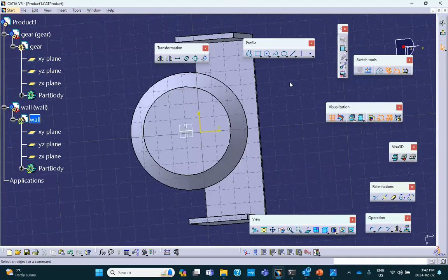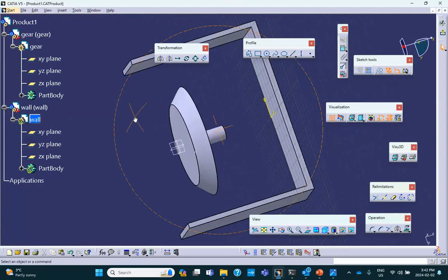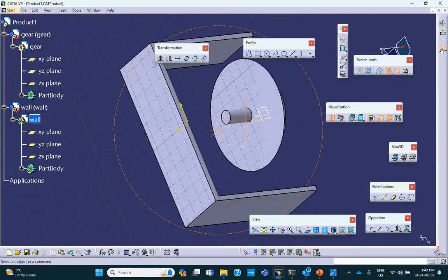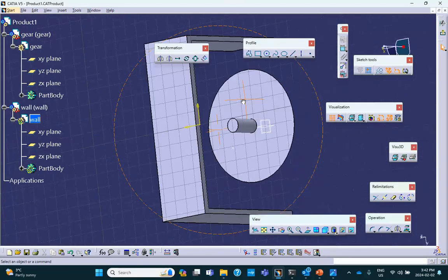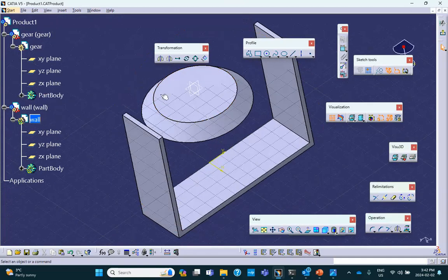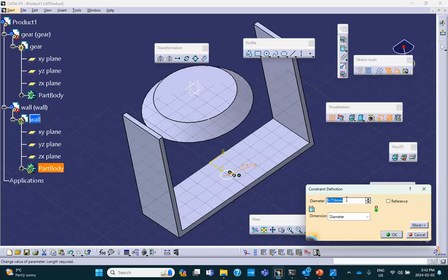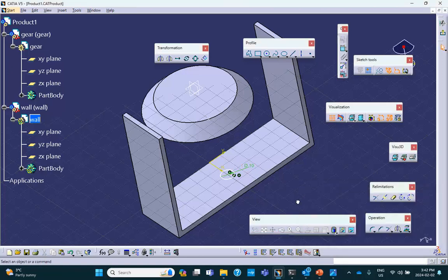and to make my job easier, I'm just going to project that. I think that is at the right spot, or maybe it's easier if I drew it. So I'll just draw a circle of diameter 10, or radius 5. And you know what? We're going to make it halfway between the top and the bottom. So left line, right line control the center. We're going to make it equidistant.